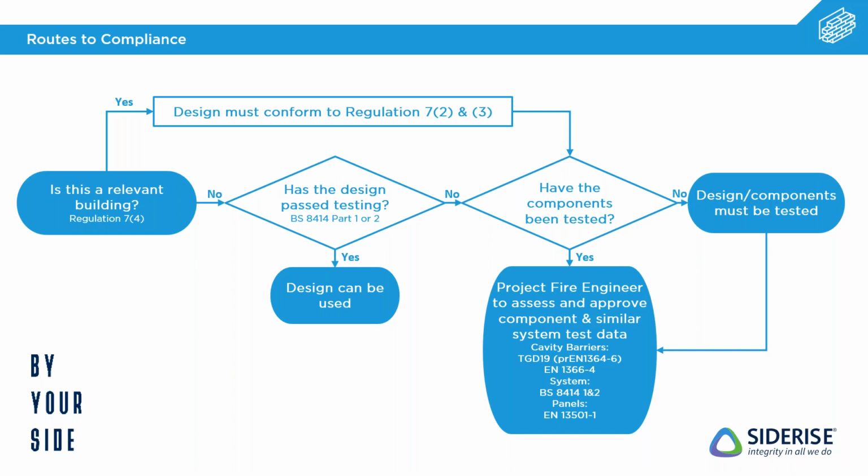However, with Regulation 7, that overrides any sort of essentially pass marks where it may involve combustible materials. So in other words, regardless of whether you've got a compliant BR135 system, it now has to also comply to Regulation 7. But as I say, masonry, that's not as common as it is perhaps in things like cladding.